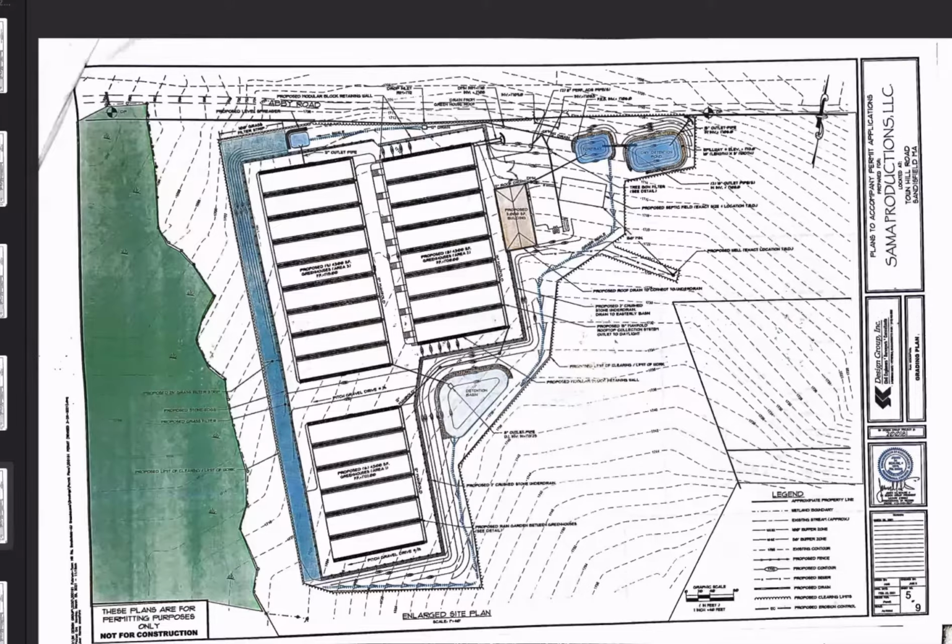Not within 75 feet of any intersection. We're about 1,100 feet from the intersection. The grade going into the site has to be less than 12%. Ours is 8 to 10%. Abbey Road is not paved, and thus our apron and driveway do not need to be paved. A 15-foot drive is required. We propose a 24-foot drive.